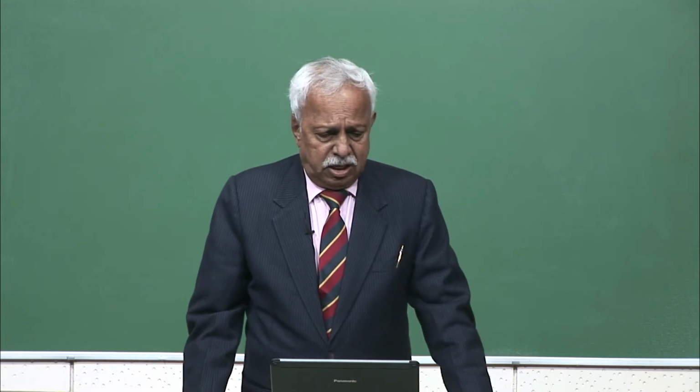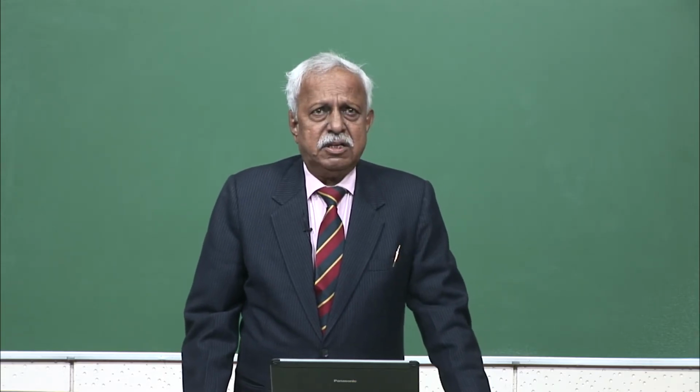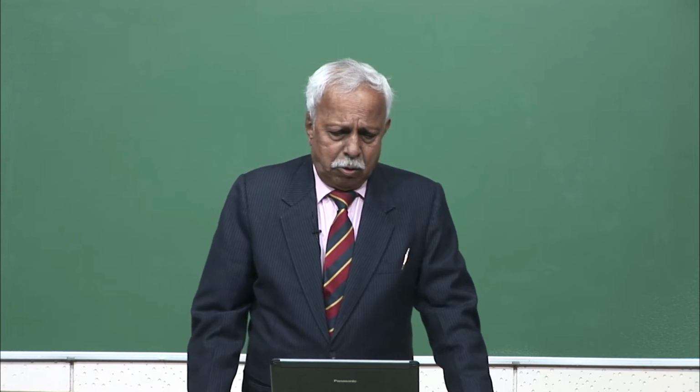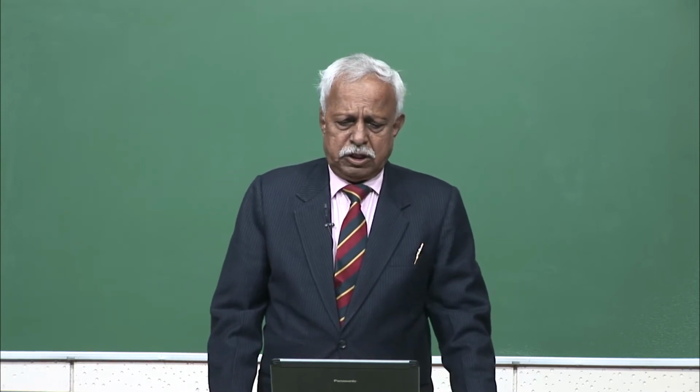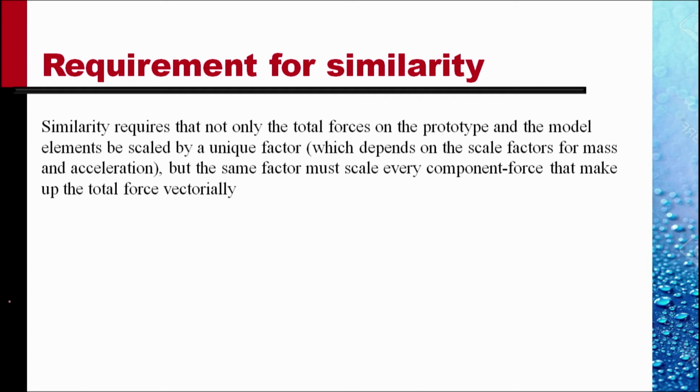In the last couple of lectures, we have discussed that similarity requires that not only the total forces on the prototype and the model elements need to be scaled by a unique factor which depends on the scale factors of the mass and acceleration, but the same factor must scale every component force that make up the total force vectorially.